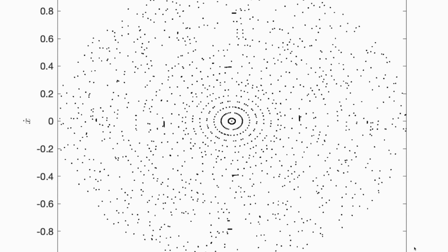Alright, so here is the Poincare map for the linear oscillator. We've computed this for many, many energy levels. E here is our equivalent H. And the way we've done this is that we first postulated that there is some initial velocity in only the LO or only the NO, and all other initial variables are 0. We then compute the kinetic energy for that initial velocity, and then we use that kinetic energy as our energy level for the Poincare map. And that's what you'll see when we have a V0 up here and an E as well.